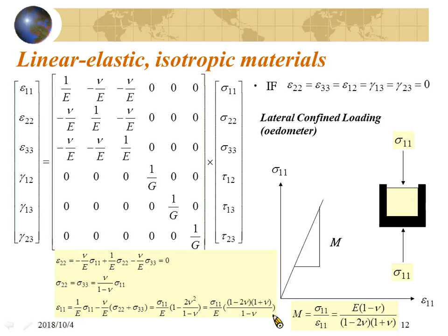The difference lies in the stress and strain condition in the horizontal plane. For the previous condition, for Young's modulus, the horizontal stress equals 0 because it is a uniaxial compression test. So the lateral stress equals 0. For the one-dimensional consolidation test, the horizontal strain equals 0.